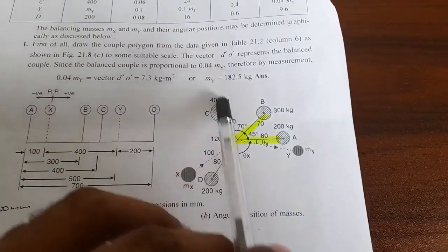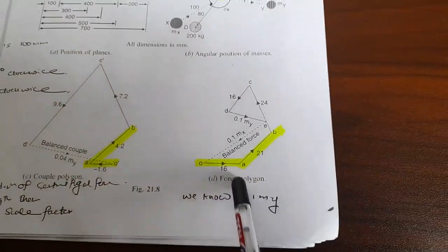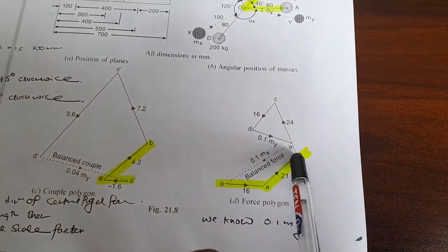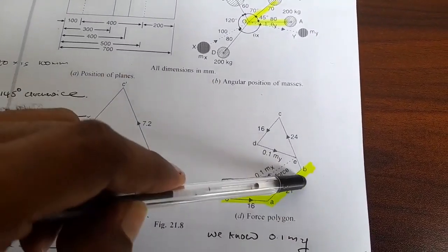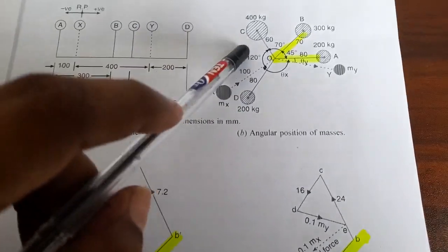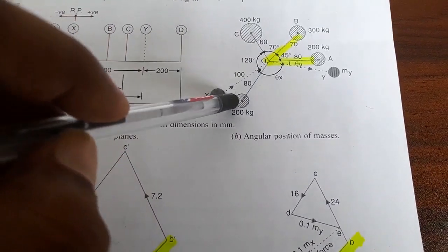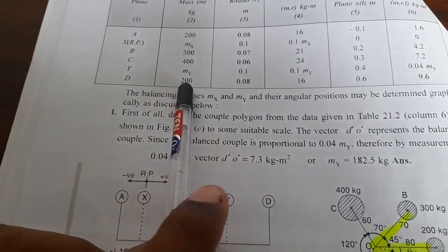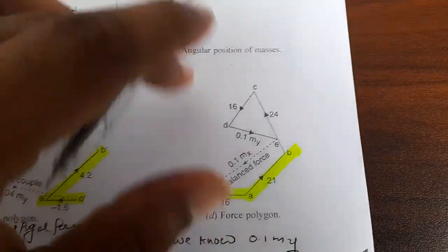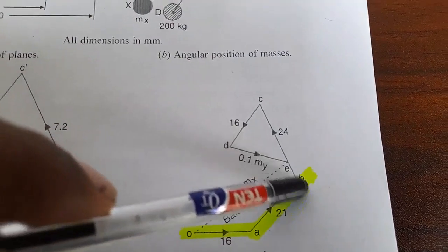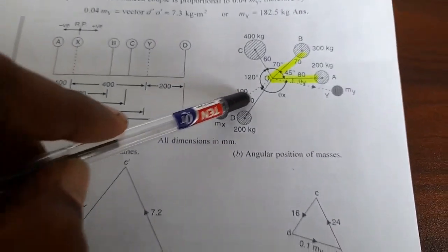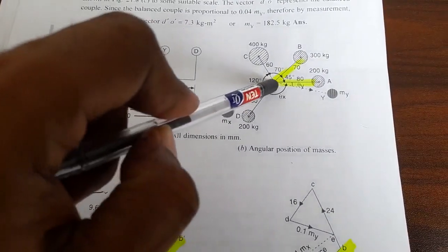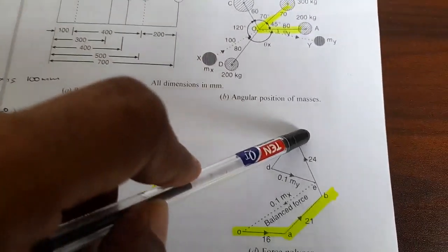24 units. C is here, right? So after reaching this point, now you can complete BC. BC is 24 units, right? It doesn't matter, before that we can compute this centrifugal force because of the 200 kilogram mass over here. That is 16, right? Now after computing BC, you can sketch this 16 down. This is the mass over here. The centrifugal force is directed away from the center. Now you can sketch this 16.